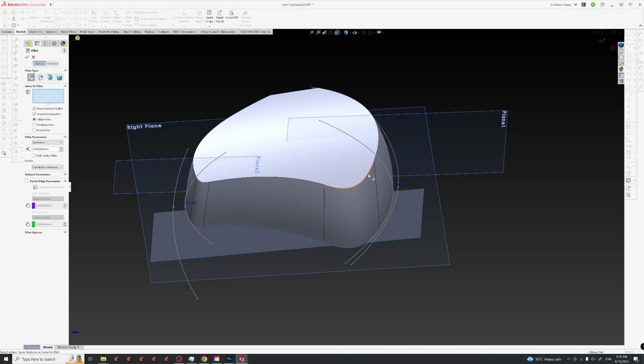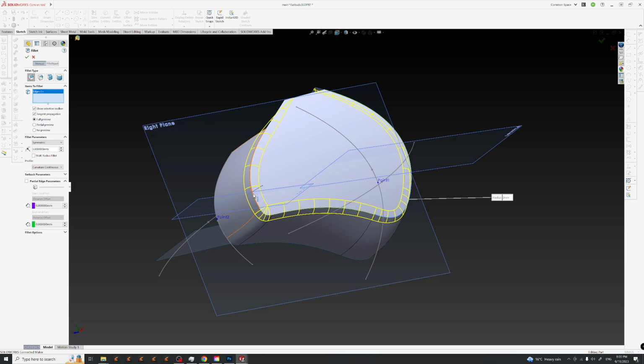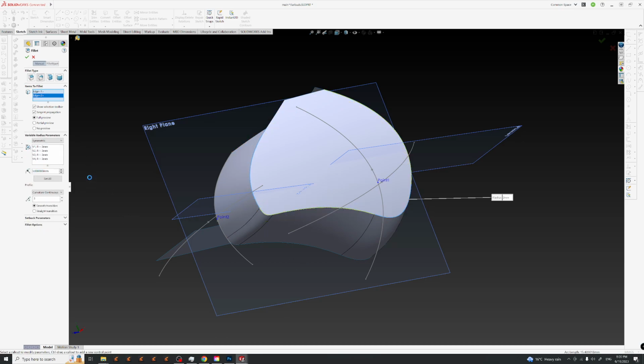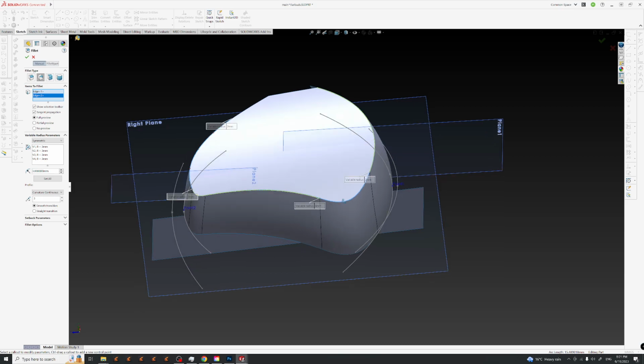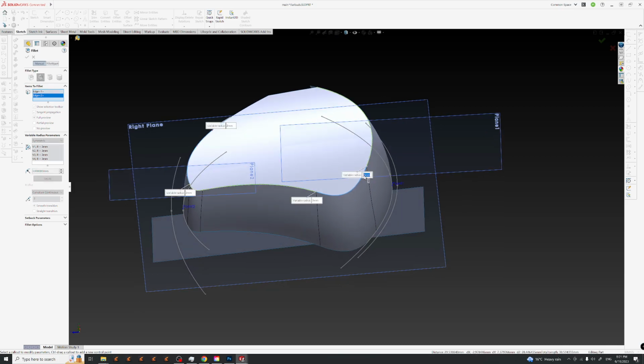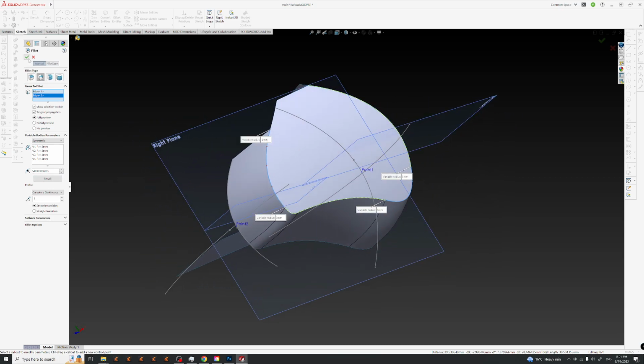I know that is a little bit more. There you go. It should be a little bit more stable. So I'm selecting 2 edges. I did see that it's not quite the same fillet all around, so I will try a variable fillet first. I'm having 3 millimeters in here. I want 5, and I want still 5. I want to go towards 3. Let's see, is it going all right?